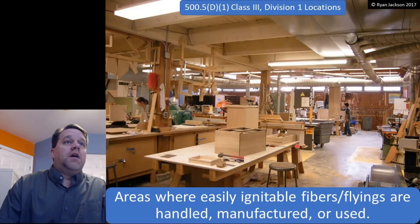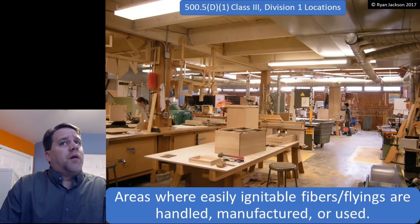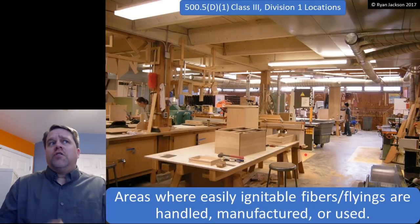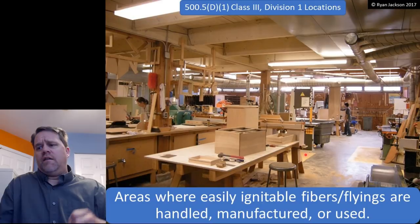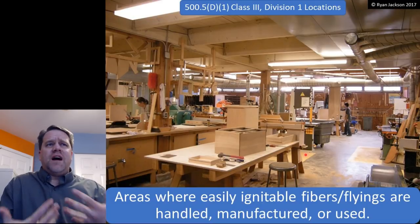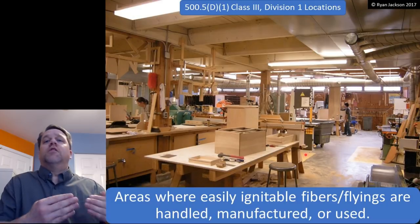So if you've got a disc sander, a belt sander, something like a drum sander, that's going to probably be a Class 2 location. But if you have a table saw, you're not really creating much combustible dust. You're more creating easily ignitable fibers or flyings. Or if you have a jointer or a planer or a wood lathe, that's probably a Class 3 location. Same material, wood fibers, but larger.